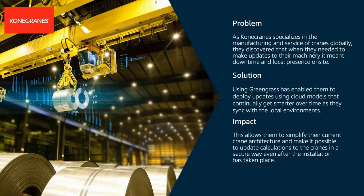But what they're able to do is understand how these cranes are being used in real time. They're able to build predictive maintenance plans, in case a crane might be failing, to understand when a failure might be occurring. A single point of failure many times on a crane is that hoist. If they're able to understand how many times it was brought up and down, they can do that predictive maintenance plan, and not just look at maintenance schedule capabilities, but understand the right maintenance plan.